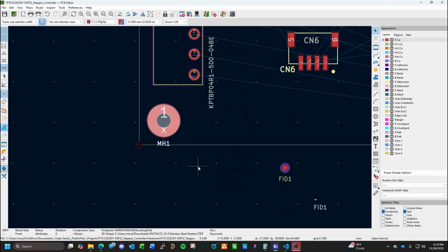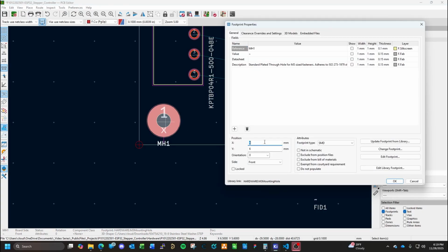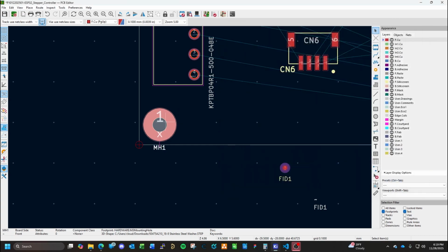Okay. That should be all right. Should have enough pullback from the edge of the board, at least 5 millimeters. We could probably push it back a little bit more. I mean, yeah, you should be fine because the actual hole itself is far enough away. That should be a minimum half a millimeter right there to cover for the pullback and everything. So yeah, we'll go ahead and accept that.